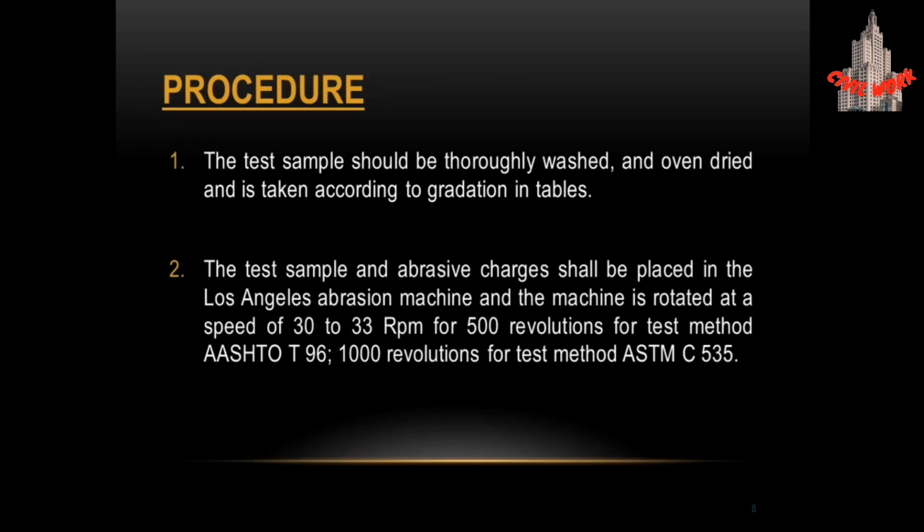Coming towards the procedure, number 1, the test sample should be thoroughly washed and oven dried and is taken according to gradation in tables.